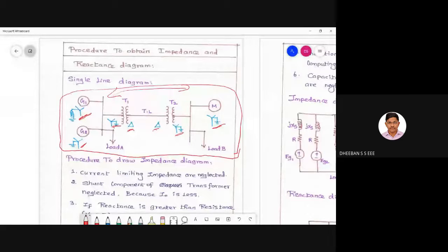While solving problems, many of you will make mistakes in this transmission line part. They will take this star, and then consider this also to be a star. Generally what happens is they lose a √3 component in the problem. So you have to be very careful about this configuration.